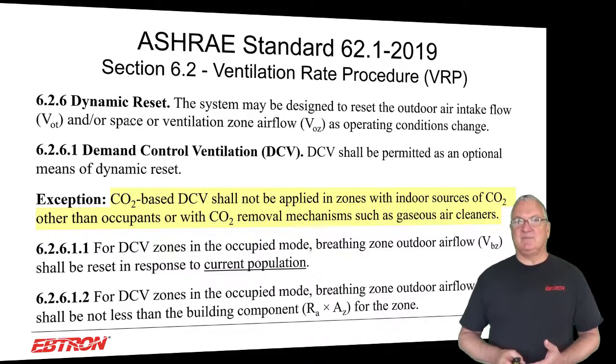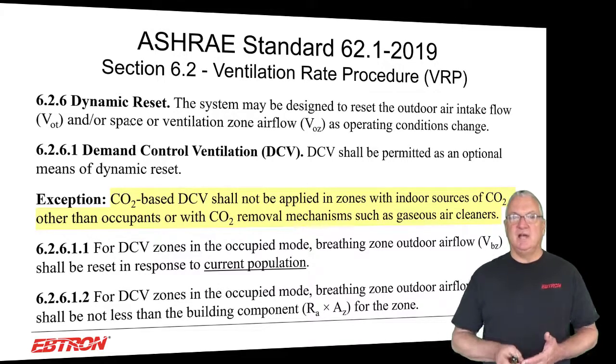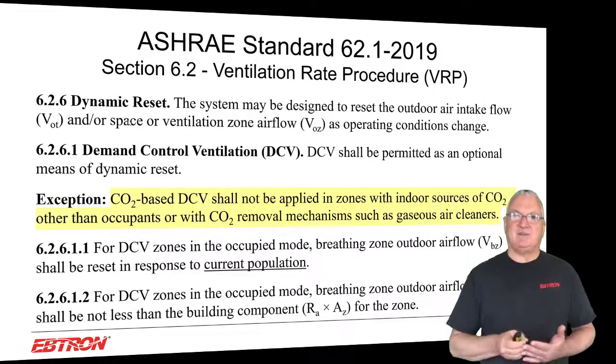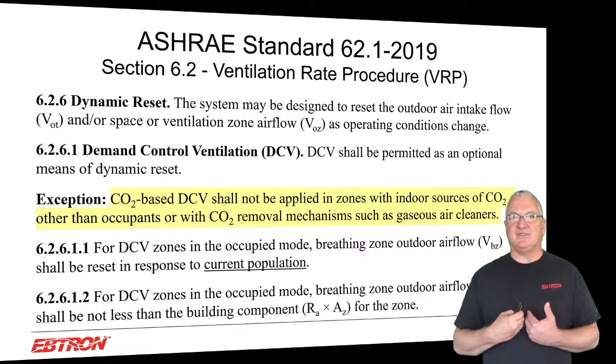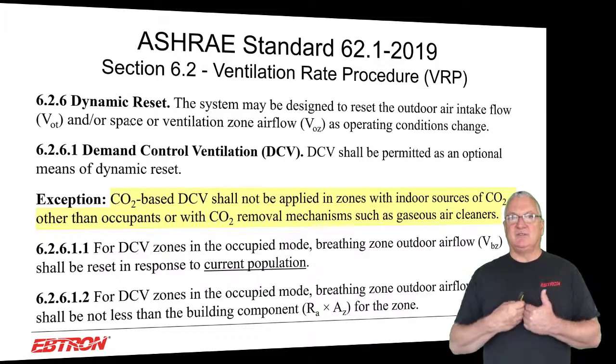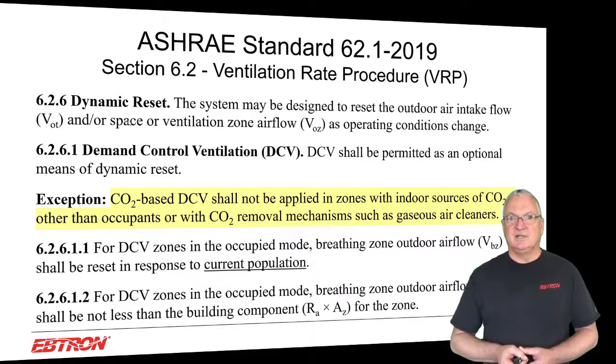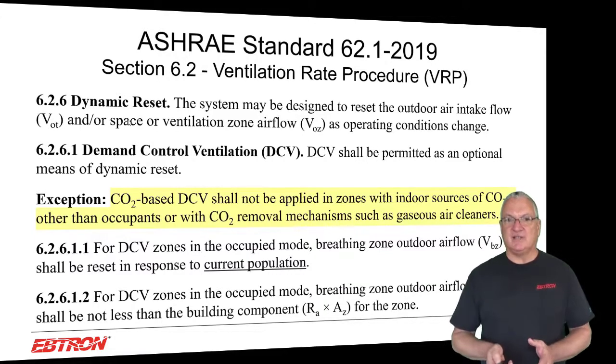You should realize, because we're using CO2 as an indirect way to estimate how much outdoor air CFM per person is coming into the space, based on the relationship with the CO2 production of the individuals. That's what you're doing, all right? So anytime you're falsely altering the CO2 level, you've changed the relationship.